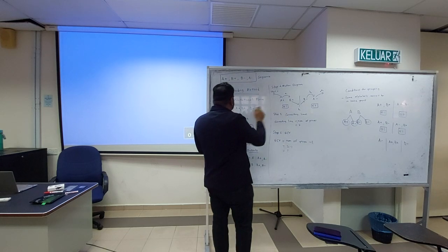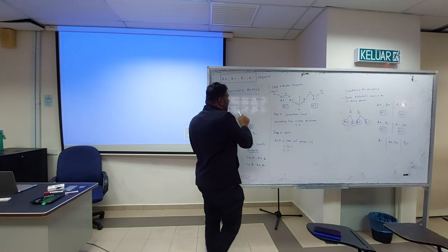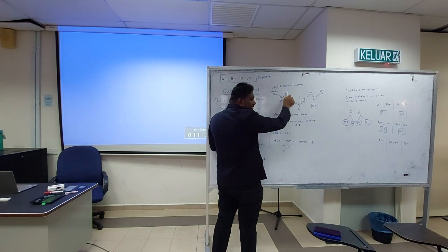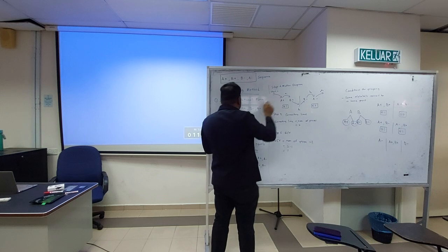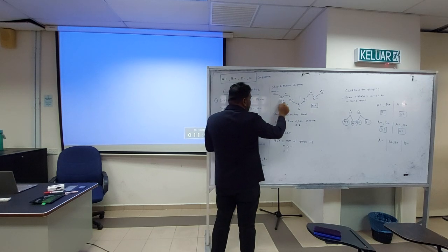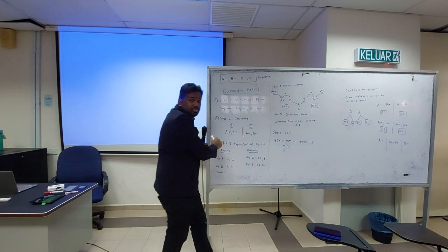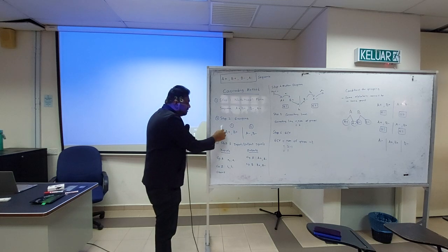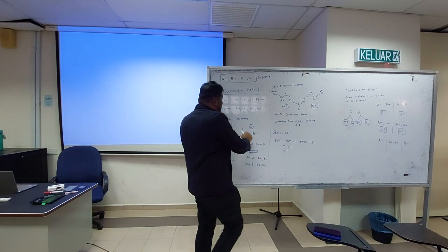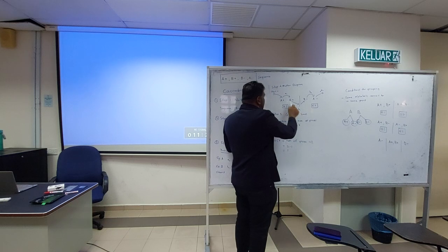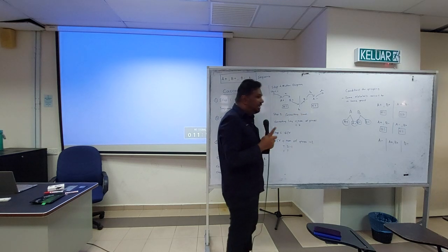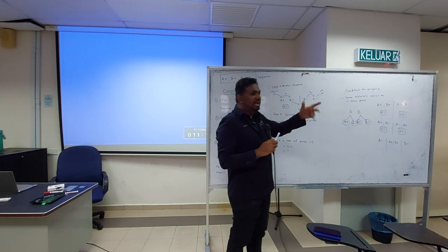So cylinder A extends, it turns on switch A1, and switch A1 activates B plus. This is the same group, so you don't need to switch group. After this finishes, it activates B1, and B1 activates the group changing valve, so it changes the line.